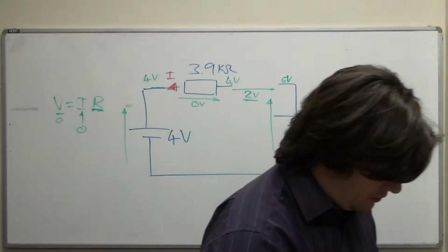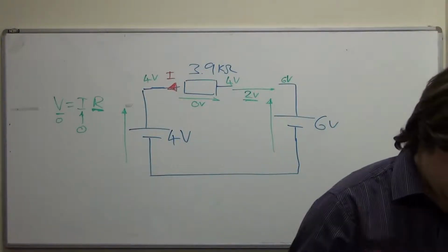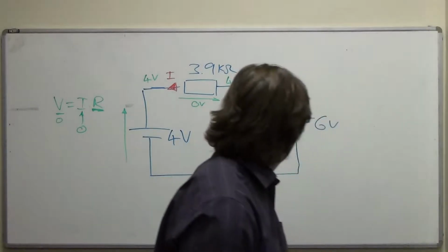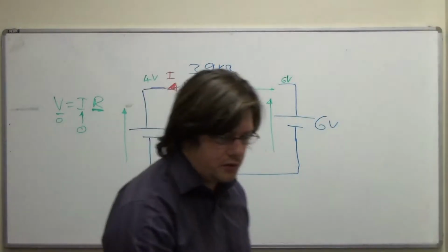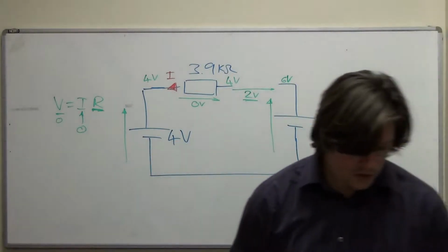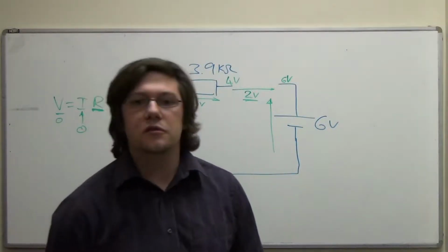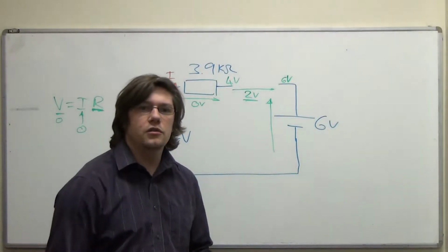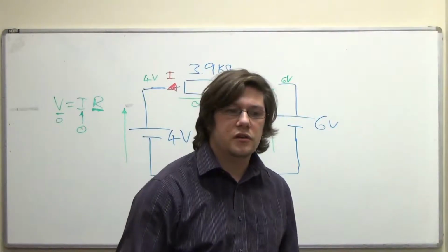So if that's the case, then our diode, which we've taken out and replaced with an open circuit, has 2 volts across it, and if it's a silicon diode, and the question says that it is, and the question also goes on to say that you can assume that the turn-on voltage of your diode is 0.7 volts, and if you reach 0.7 volts, you may assume that the diode switches on immediately and conducts any current that the circuit will permit it to.